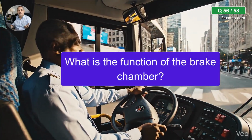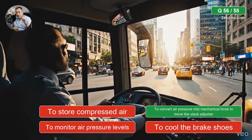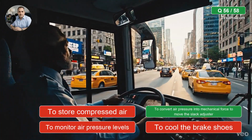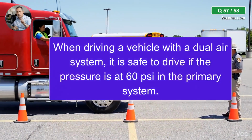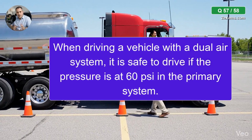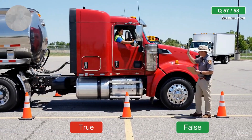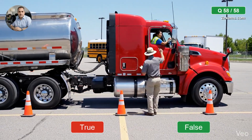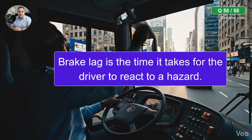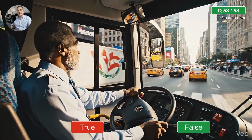What is the function of the brake chamber? The correct answer is, to convert air pressure into mechanical force to move the slack adjuster. When driving a vehicle with a dual air system, it is safe to drive if the pressure is at 60 psi in the primary system. The correct answer is, false. Brake lag is the time it takes for the driver to react to a hazard. The correct answer is, false.